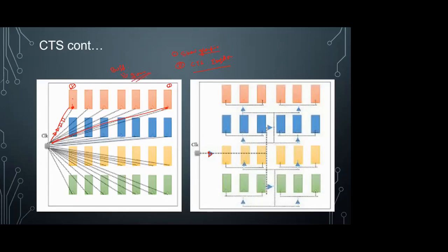Sir, if we use an inverter, it will occupy more area, right? Because the size of the inverter pair will be high, right? See, for example, here I have A and here I have B. Instead of using buffers here, I might be using some three buffers or something like that. So instead of this, I can use an inverter pair only, one inverter here and another inverter here. That will be helpful. Inside the buffer also, we have the inverter pair, and the drive strength is also very important.